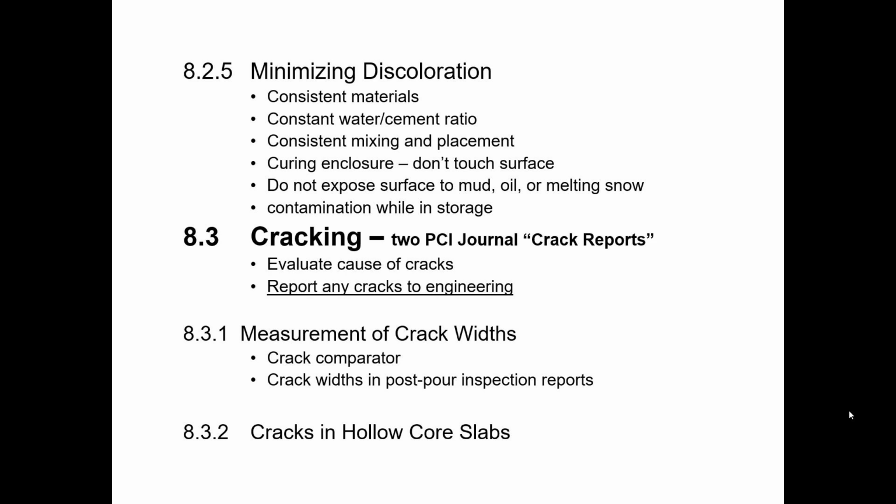If that doesn't work, you can maybe up the ante a little bit by scrubbing it with a brush and then using a low pressure washer to try to rinse that off. You could use chemical cleaning compounds. There's different detergents or even phosphoric acid or other chemical cleaners that can be used if they're used in the right way.